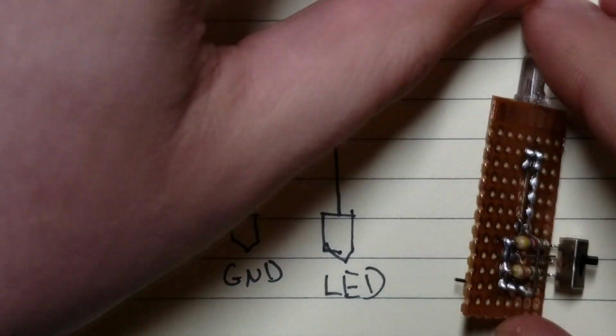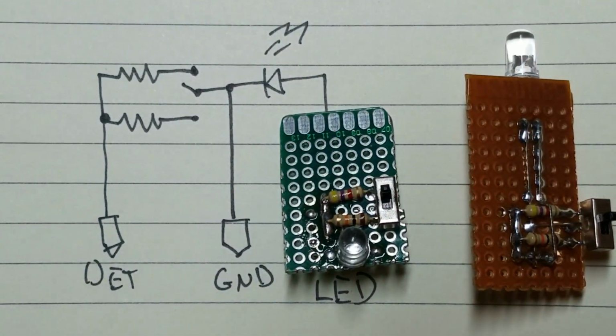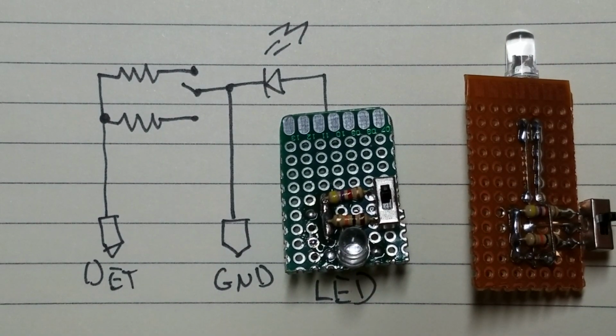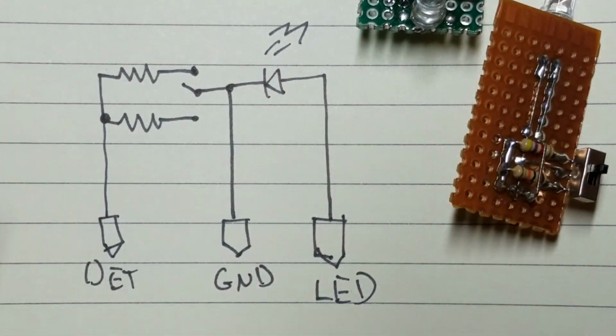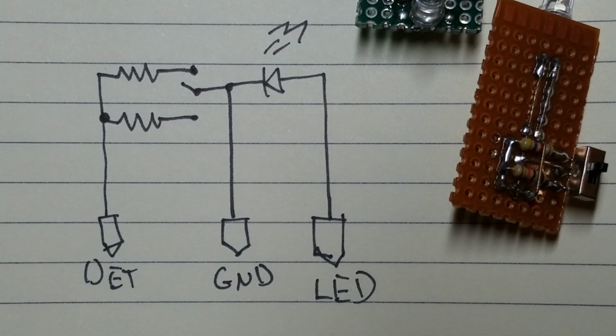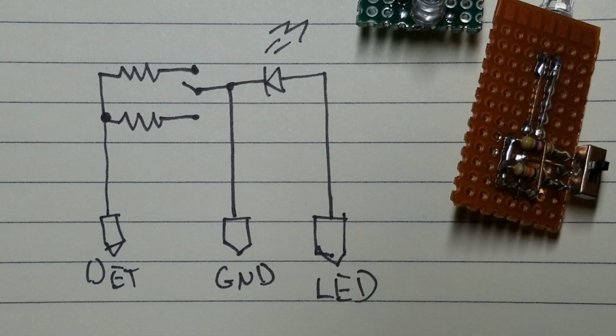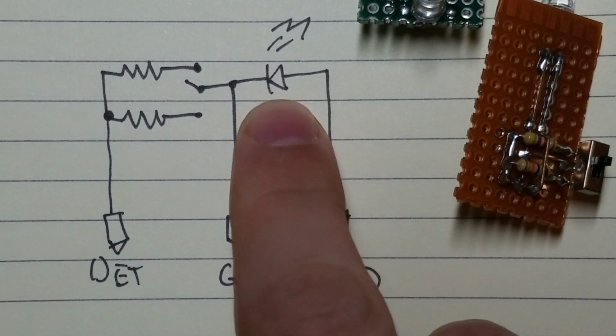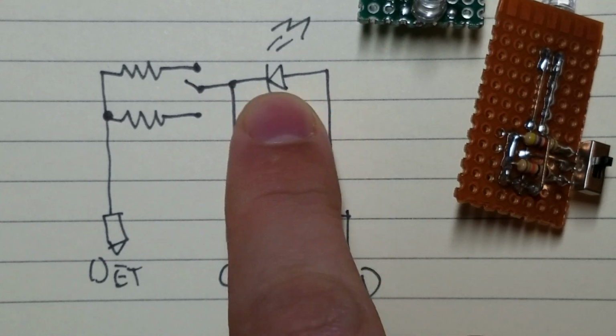Which opens up, by the way, the possibilities of making custom accessories. Totally doable. If you start thinking about doing something like that, one thing to note, the LED pin on the internals, the electronic internals of the droid, already has a 100 ohm resistor in line with the LED to limit current through the LED. If you want a slightly dimmer LED, or if you are using an LED with a lower forward voltage, like a red LED, you probably want to throw in an extra 100 ohm or maybe 220 ohm resistor in there, just to reduce how much power is going through the LED.